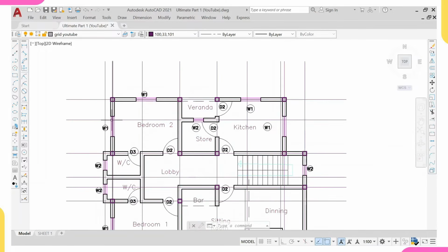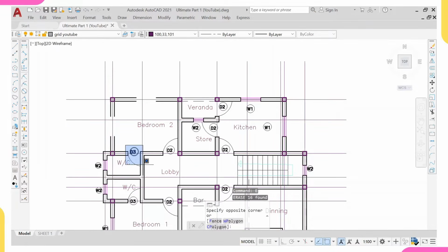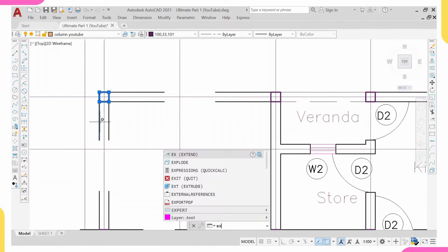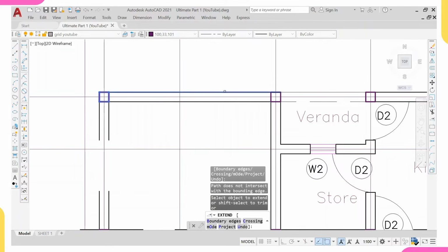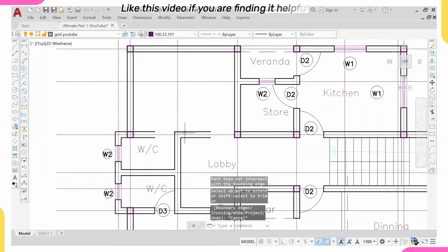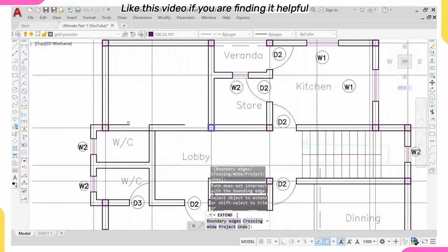I want this whole place to be one panel. So since I want this whole place to be one panel, I'll delete this, delete this, enter. I will also delete this, and this. Enter. I'll also delete this setting. Then I'll click on this point and do ES, which stands for extend. I'll click on this line and extend it. Then I'll click on this line, and this line. Then I'll erase. I will highlight this column, then click ES, which stands for extend. I will extend this line and also extend this line.